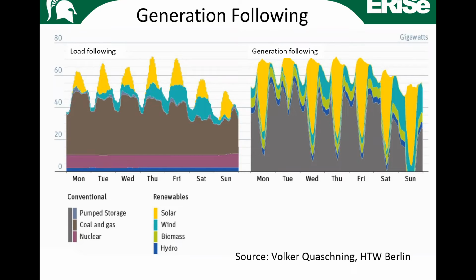So there's base loading generators, okay, mostly coal and nuclear and things like that, that run 24/7. And beyond the base load, they vary a little bit. That is picked up first by what are called intermediate generators, and then by peakers, okay. And a lot of these peaks could be picked up by wind and solar and other renewables, but otherwise, we also use small gas turbines and diesel generators to do that. But this is the conventional approach to balancing generation and load.